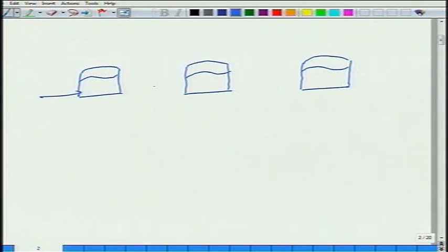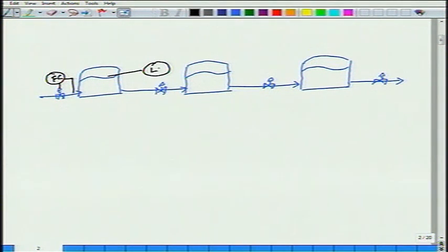And it is just a simple tanks in series. Alright, you got all these valves. In the absence of any other information, I decided, like a simple minded chemical engineer, okay, this will be my throughput manipulator, in which case the level control would be this way.